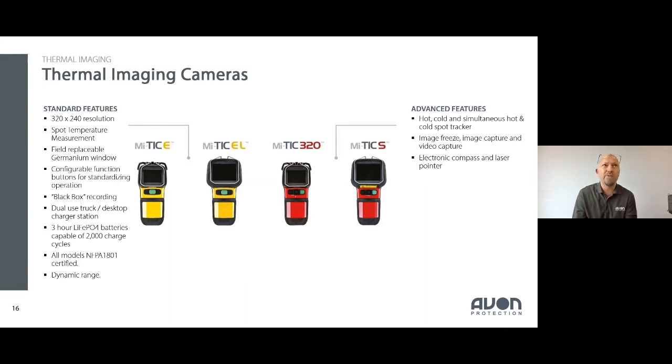We have a spot temperature measurement as standard. That is going to be changing in the new NFPA 21, so that will be a feature that we change. The NFPA organisation don't want a spot temperature moving forward, so we will put that on another mode, which I'll talk about in a minute. We have a field replaceable germanium window, which I talked about briefly. And then we have configurable buttons for standardizing operations.